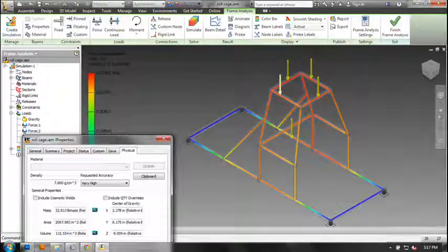With the simulation run, you can see that the deflection on this particular frame was about 0.01 of an inch, with 200 pounds of force being placed on the halo. You'll also notice that I've opened up the iProperties window, which estimates that this frame will weigh about 32 pounds when completed.